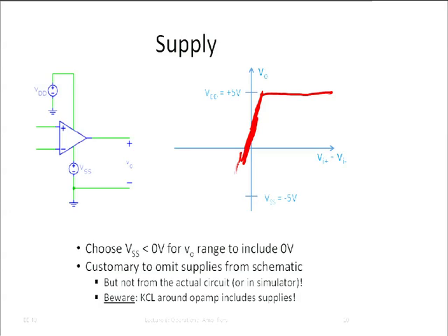That's the output voltage here versus the input, the difference of the input voltage. That's this difference here. Okay? If it was really infinite, then this would be just like this. Okay? But it will stop at the supply voltage. And so, for example, this could be 5 volts here, and this one here may be minus 5 volts. Supply voltage that we have to hook up to every actual operation amplifier.